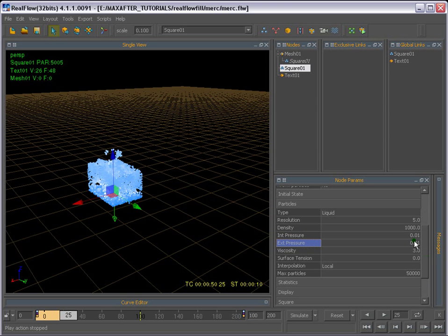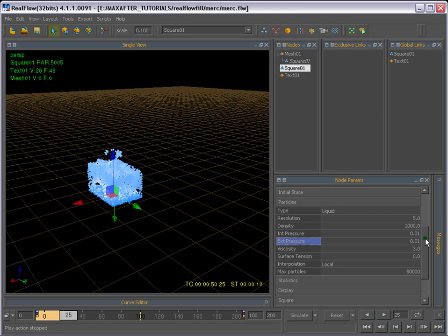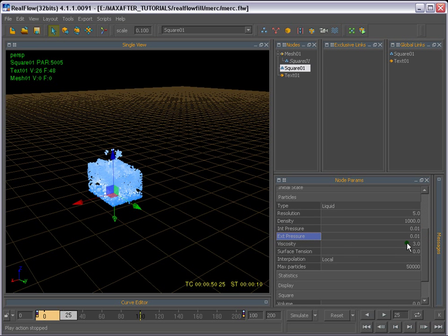These are the settings that I've explained earlier in my previous tutorial in more detail. You can refer to that tutorial as well. And viscosity, we know the viscosity of water is from 1 to 5, so we'll use 3, and honey, oil and others are more than 5. The surface tension leave as it is, and maximum particles, let's change this to 100,000 to get better results.